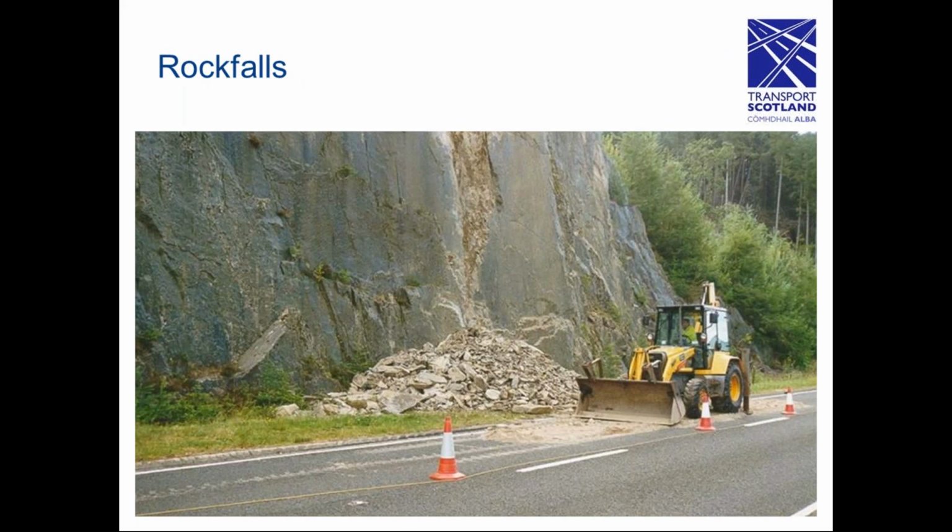I should also mention that as well as landslides, we have a significant potential issue from rock falls. And we've carried out a very similar risk assessment approach to identifying the high priority areas for rockfall risk. And we've been carrying out a program largely of hard engineering of bolting and netting to, again, mitigate the risk to road users.